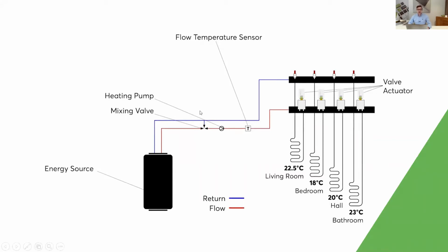On this heating layout as well, we will also have a pump, a pump that you would typically have at a manifold. And we're also going to include a zone valve as well, because you would usually have one or more zone valves. We're going to do it so that the zone valve relay is wired to the pump, so we would only need to trigger the zone valve. And then over on the manifold, we've got valve actuators on each loop, and then a loop feeds each room.